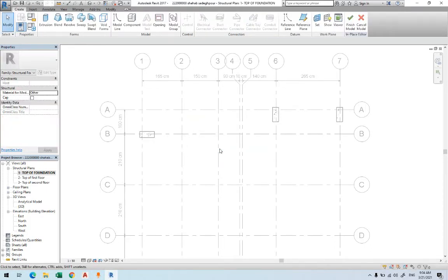So when you click on the name you wrote, mat foundation, you will have a completely new Revit ribbon. Now the ribbons changed. You have create, insert, annotate, and some of them are similar, but the first one will be create. No longer do you see the rest. Why? Because you are in model in place. I mean, you're modeling something in the project. Now what do we have? The main things, we have the forms. Those forms are used to create the 3D objects.